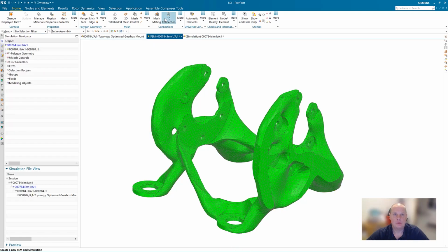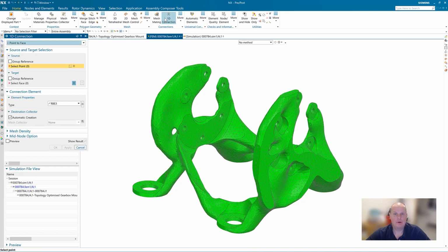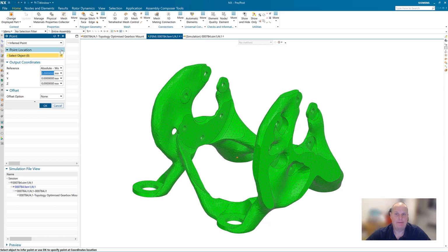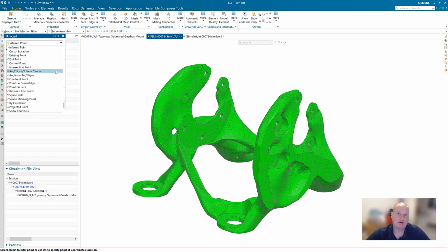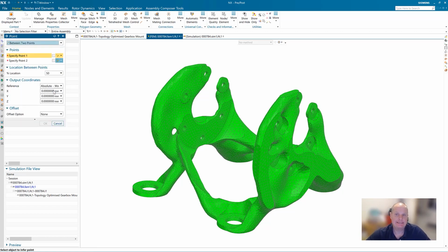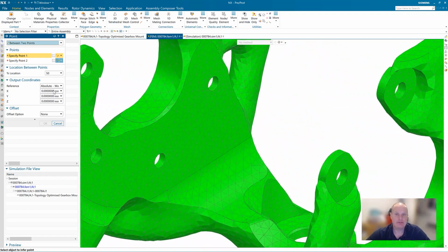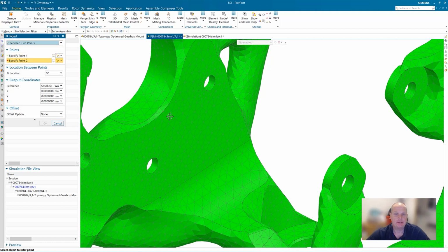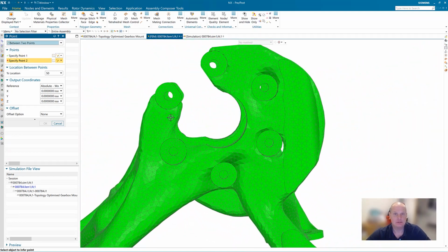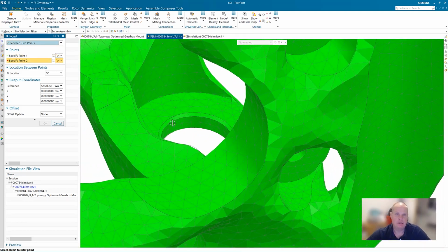time. Now we need to create a rigid element with its base node at the approximate location of the center of mass of the gearbox that attaches to this mounting bracket. We don't need to be exact for this analysis, as we are only trying to provide baseline guidance to improve the quality of the design.